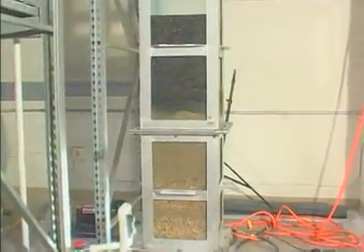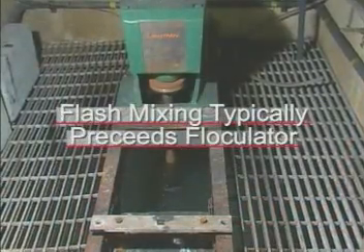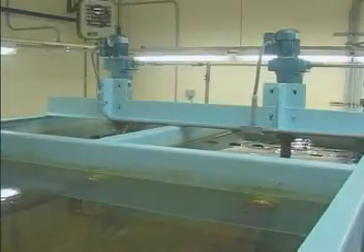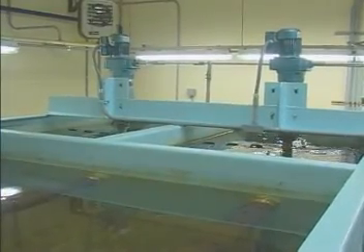As mentioned earlier, conventional filtration uses flocculation, sedimentation, and filtration processes for filtering the water. The purpose of the flocculator is to mix the coagulant chemical and the particulate matter, then to promote the contact and growth of these particles as they begin to adhere together. For this reason, flocculators often are staged in series.